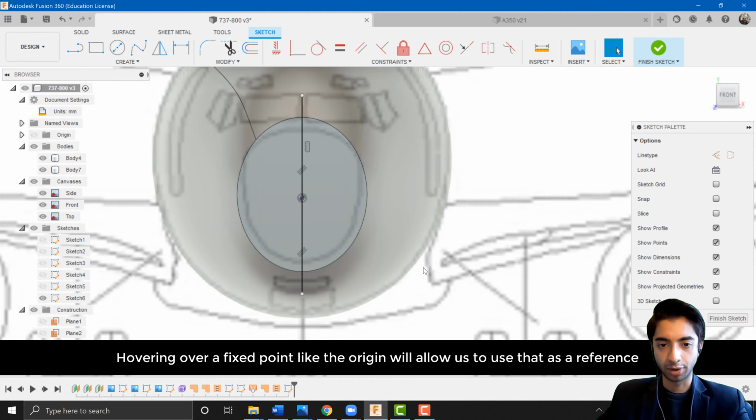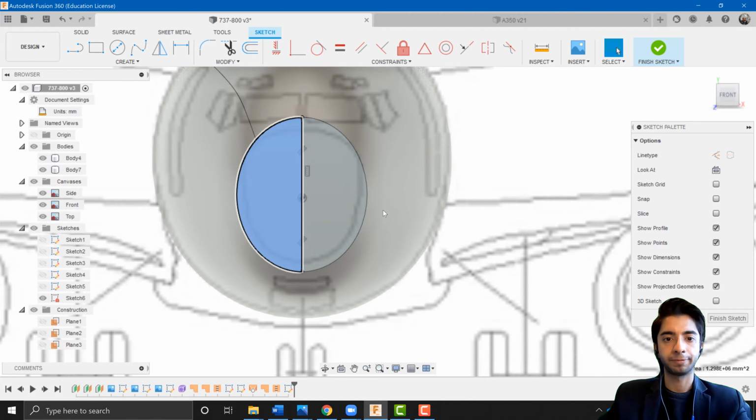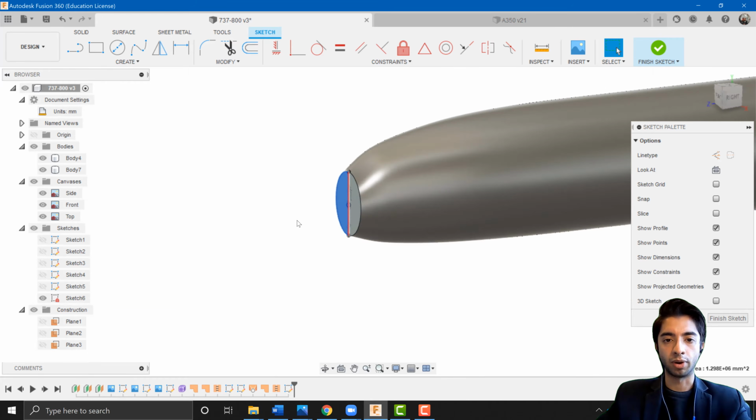Now I'm going to press T again. So once you're done with the tool, press Escape. Then you want to press T, and then you want to get rid of this line and that line. So again, if you press Escape once you're done with the tool, you should see that this has been split perfectly in half. All right, so that's step number 1 done.